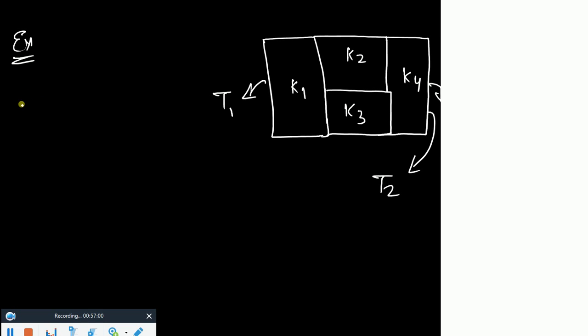Come on, how would that thermal resistance network look like? You can just start from the temperature, just like you start from the voltage in the electrical circuit course. You would have one thermal resistance. Why? Because the whole heat transfer rate would be going from this side. Then at this point it would be divided into two.